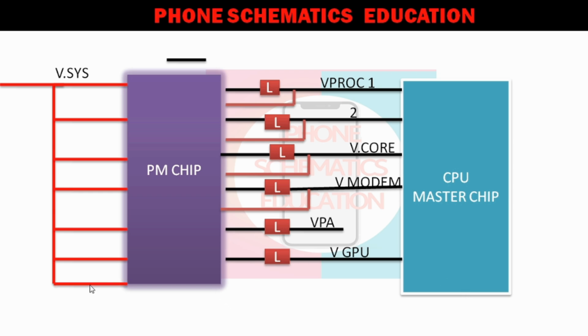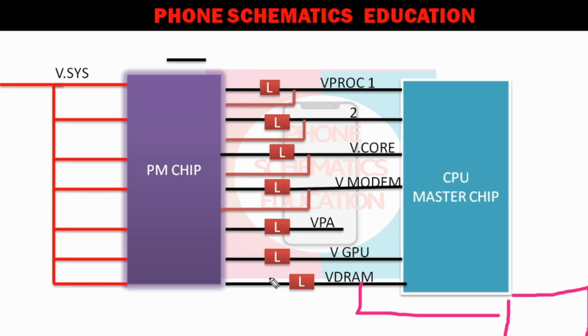So, there is an input voltage of 3.7 to 4.2. Now, another line is generated called VDRAM, right? It goes directly to the CPU, right? Also, this line goes to the eMMC IC, right? Also the power IC. All these lines have a feedback. I am not drawing it because there is less space, right? On this line, you get 1.2 volts for RAM, right?